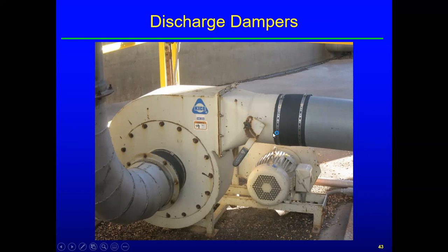And if this handle was parallel with the duct, so if it was raised up here, then it would be 100% open. Now, you do have a slip coupling here, so if you can shut this thing down, or if nobody knows, you could take those screws off and probably get in there and look at this one pretty easy. So that would be a possibility.